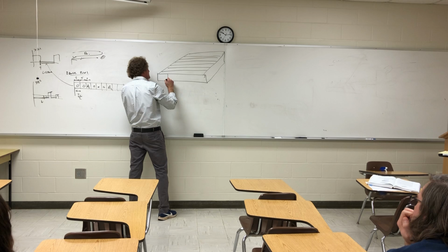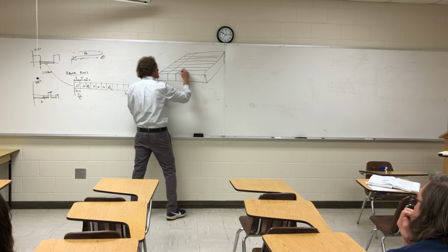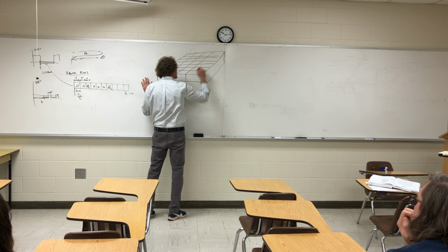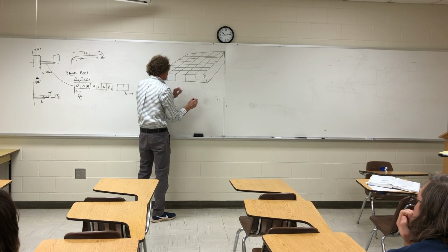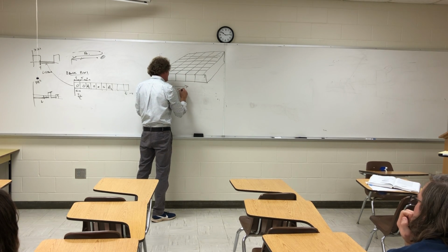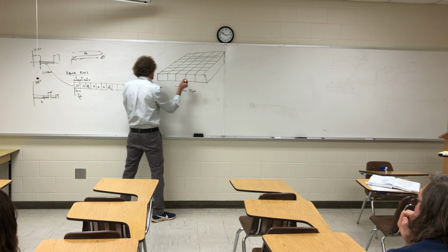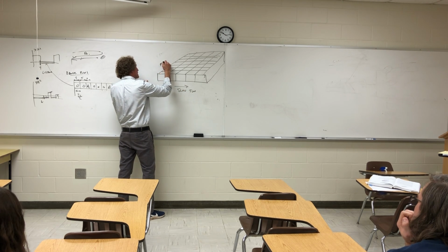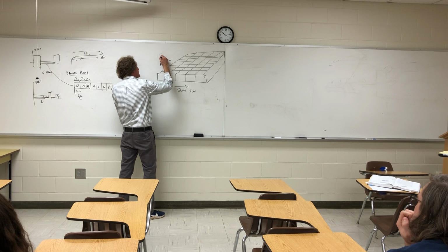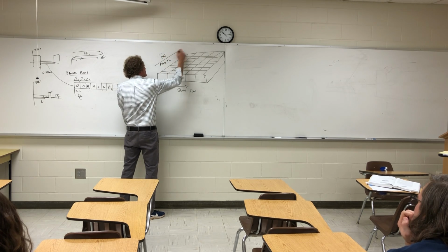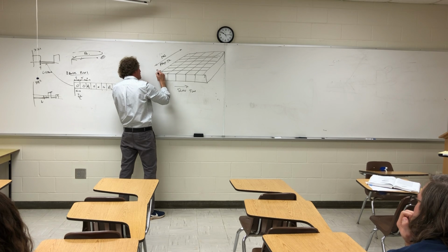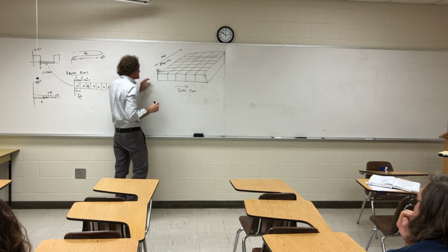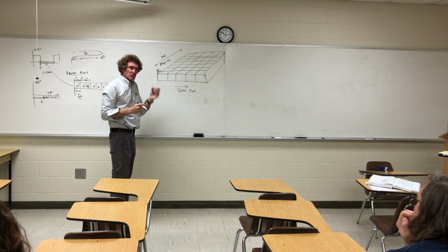And then they'll have this. You all know what I'm doing here. I'm basically parsing this thing. And then, basically you're going to have a row. This is slow time, write that down. And this is fast time. And this is the PRI right here. This is the full length of the PRI. The width of this is at least tau times C over 2. Usually it's smaller than that, but that gives you the actual range.